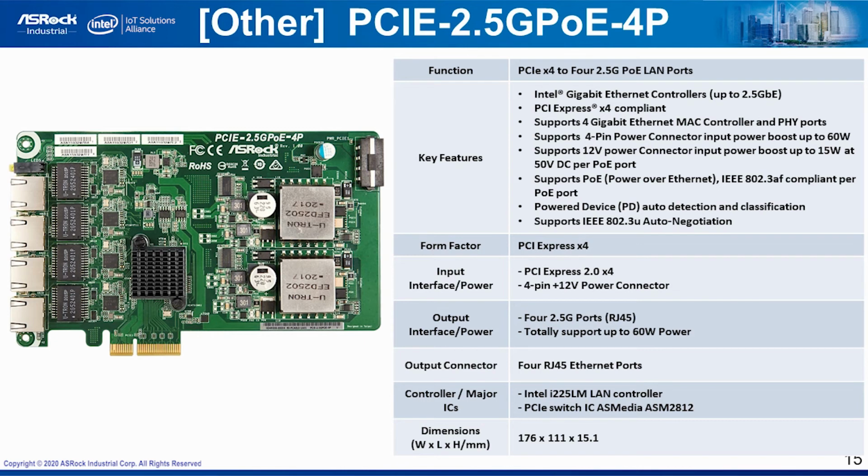The input of this card is PCIe 2.0 by 4 and a 4-pin power connector, as the picture showed. Output is 4 2.5G ports. This card applied Intel i225LM LAN controller and ASMedia ASM2812 to implement this function.